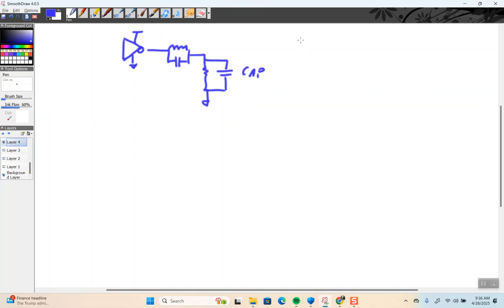So power in an inverter is alpha C load VDD squared times the frequency. Now this isn't on the exam, but if you have a 50% duty cycle, or if it's switching every clock cycle, alpha equals 1. What's the average of how much you switch?